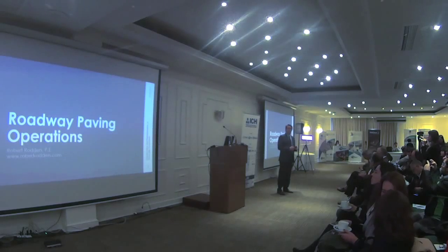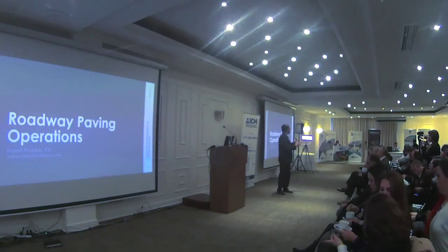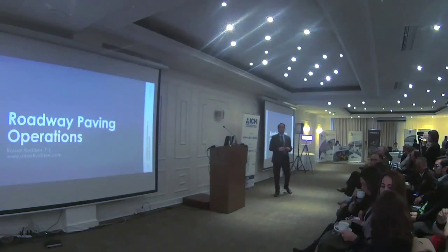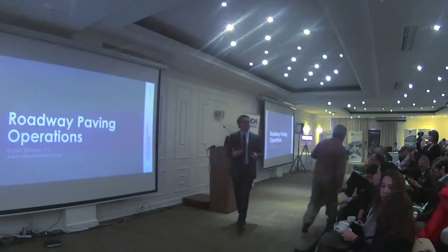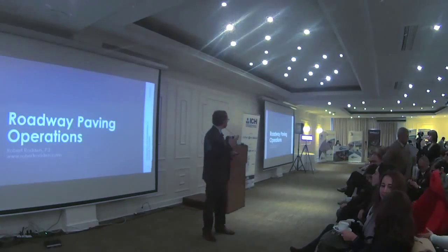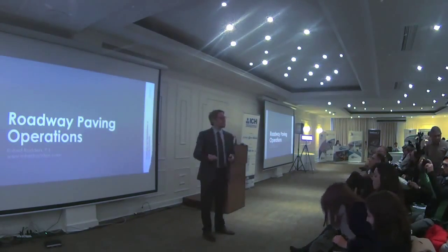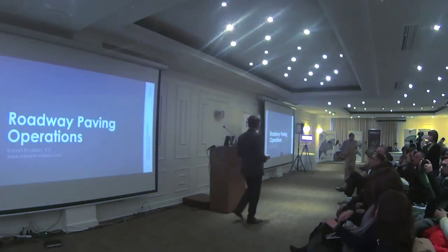Now in the U.S., slip-form pavers are so readily available that we do everything that we can with them. And we do the smallest amount of hand placements possible. Now, it takes a while to get the contractor basis to that point where slip-form paving is so standard, but once you're at that point, you're producing very high volumes of concrete roadways, very, very uniformly, and at the lowest cost possible.